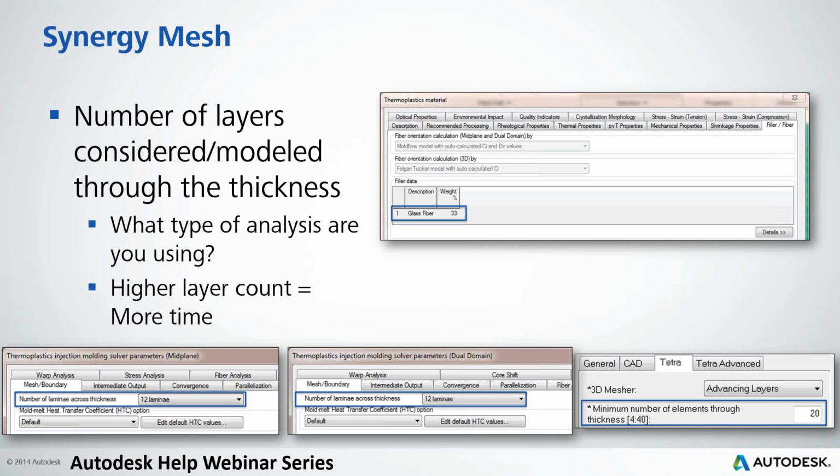That's a good question. You can do it. You can certainly take it up to 5 million elements. Again, it's basically taking the geometry into account. Do you really need that number of layers through the thickness there? What you might want to try is running with a few less layers, maybe do 10 layers at first. Take a look at the results. Are you seeing what you want to see in there? And then increase it from there. Take it up and slowly increase it.